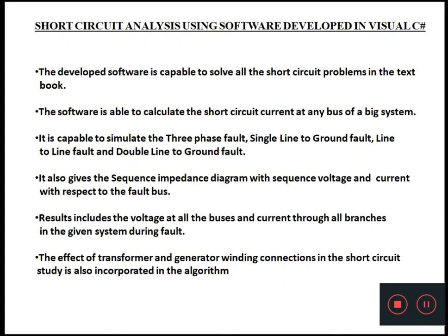It is also capable of simulating the three-phase fault, single line to ground fault, line to line fault, and double line to ground fault. The major highlight of this software is that it gives the sequence impedance diagram depicting the sequence voltage and current with respect to the fault bus. That means for each type of fault, the impedance diagram is different and the same is given by the software.